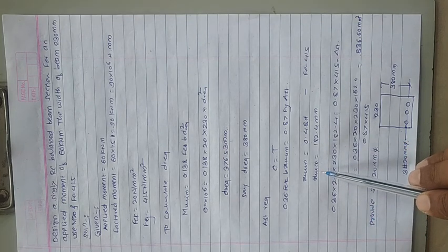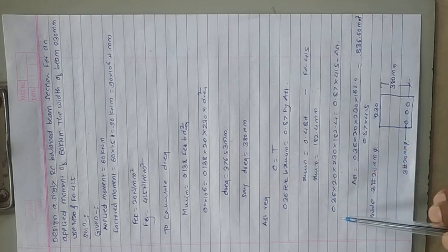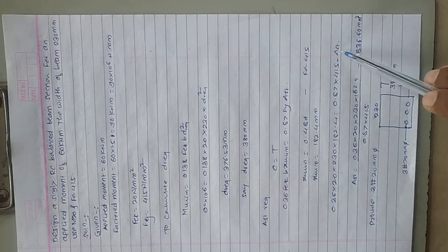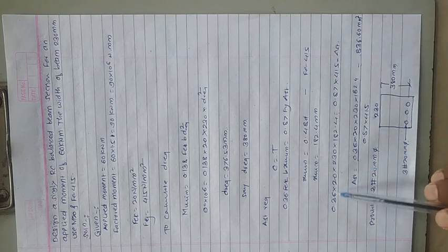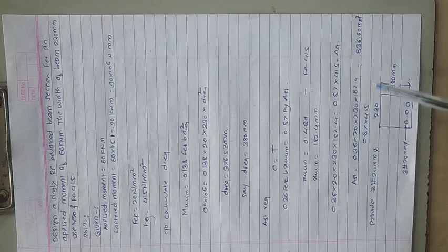So put this XU limit in this equation. In this total equation, the unknown term is only AST. By solving this equation, calculate AST. The AST is equal to 836.60 mm square. So convert this AST into number of bars. Then how to calculate number of bars? AST divided by area of 1 bar. So provide 3 bars of 20 mm phi, and this is the final solution.